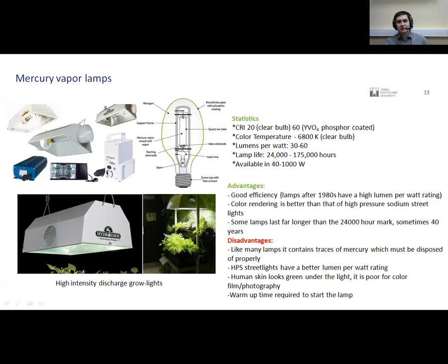The arc discharge lamp is generally confined to a small fused quartz arc tube mounted within a large glass bulb made of borosilicate. There are two types, namely high pressure and low pressure. Of course, we can separate them. In a low pressure mercury vapor lamp, a glow is produced when electricity is passed through liquid mercury.